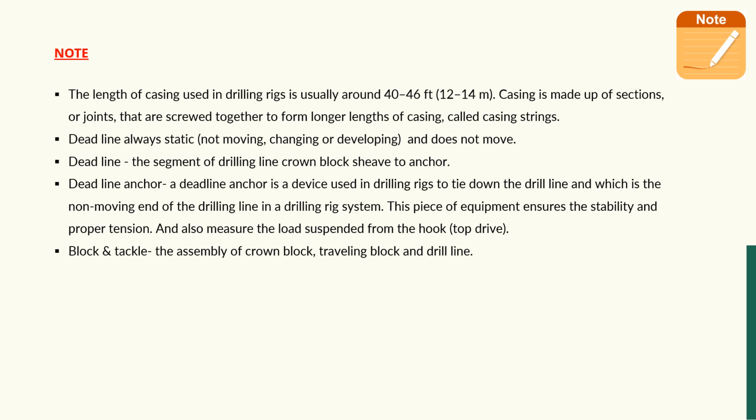Deadline: the segment of the drill line from the crown block sheave to the anchor. It means the deadline anchor. That is the deadline. The deadline anchor is a device used in drilling rigs to tie down the drill line, and it is the non-moving end of the drill line in a drilling rig system. This piece of equipment ensures stability and proper tension, and also measures the load suspended from the hook or top drive. Okay, block and tackle: the assembly of crown block, traveling block, and drill line is called the block and tackle.